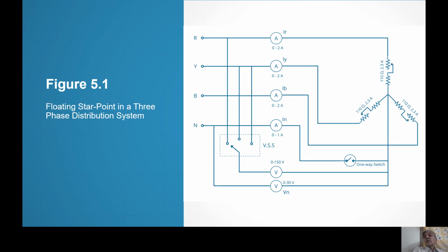You have to connect the rheostats in a variable version so that you can vary the current. Because our main point is we want to see the effect of unbalanced currents on the voltage. Now we will see why the current can be unbalanced. It's not that the current can be unbalanced; current is always unbalanced. Because the last distribution point is a society.